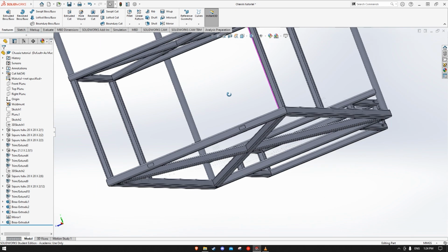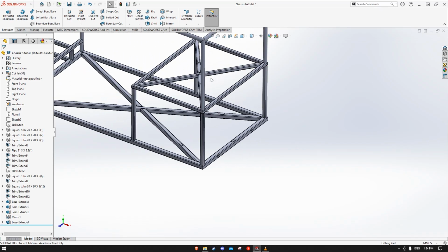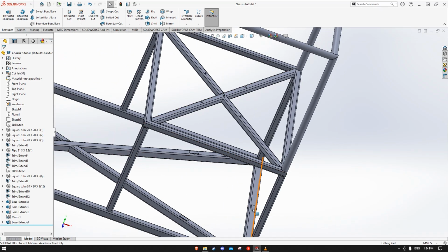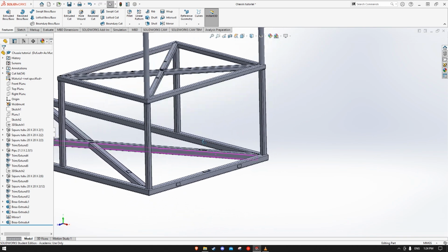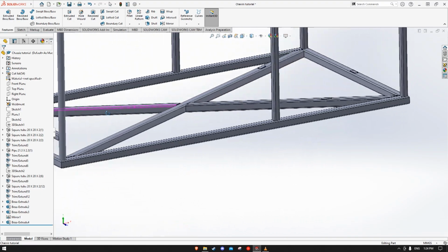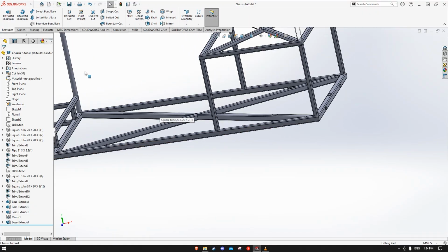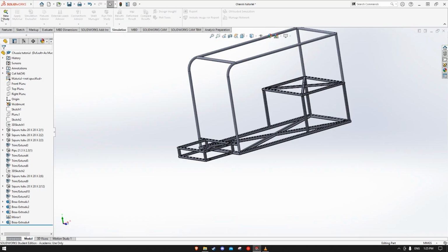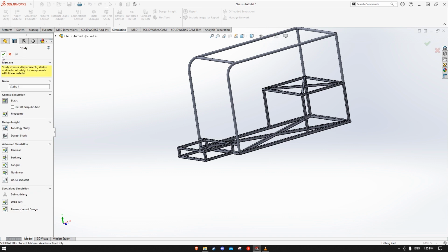So what you need to have is all the components mounting points. So I have the passenger and the engine here. 1 for the engine, 3 for the engine, and 5 for the passenger. The rear suspension or rear solid axle mounting points, I have these two, and the front suspension arm mounting points. Next, we can start with the FEA. To start the FEA, similar to the suspension arm analysis, we go to Simulation, click on New Study.